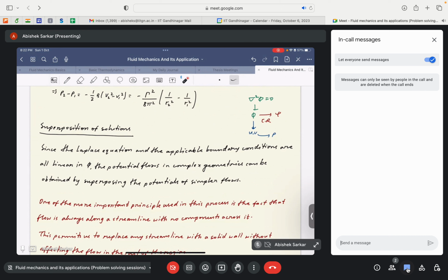All the terms, the body force term, that is not existent in the case of the Euler equation. We are not considering the body force term in this context. We can say the body force term is embedded in the pressure gradient term, and we are only dealing with the advective terms. Since the advective terms are composed of the velocity components, and we know the velocity components, we do not need to solve the convective part. The advective part is already known.